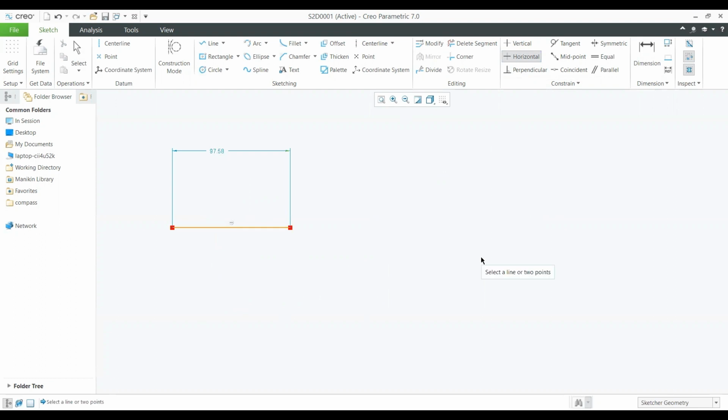Now what happens here if I create a line of a certain length and select it, whether it is a vertical line or a horizontal line, the dimension is changed. The reason the dimension changes is that we are not providing a dimension constraint, so we can easily manipulate it because we are not able to restrict it. Now see, if I select the line and put 100 mm and enter it.